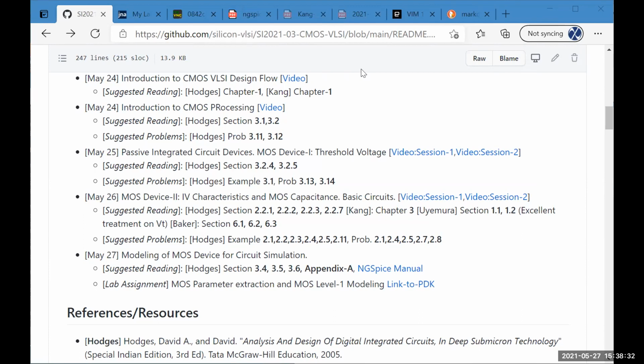You have to imagine it this way. This is a C program, right? Spice is a C program. That C program has a function, and that function is what is calculating, and all the arguments to that function are the parameters in the model or the ones you're sending through the instance line, like the M1 drain source, blah, blah, and all that, right?